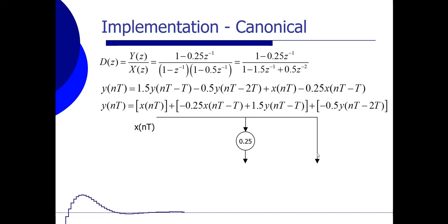So it's drawn over here. We also have an input signal which is delayed one sample, which is written over here and multiplied with 0.25, and that is this part. So here we have X multiplied already with the 0.25, and we are going to use it to implement the delay afterwards.